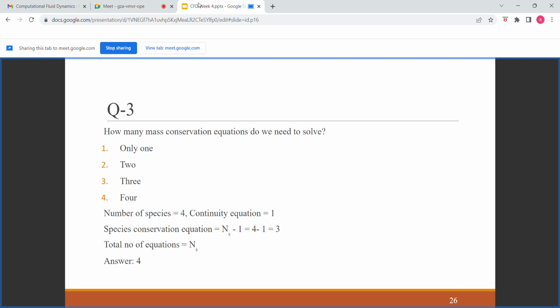But when everything is added together, we get one, so the number is one less than the number of species present. So basically 3 velocities u, v, and w, plus one pressure plus one temperature give 5, and mass fraction terms, where 4 species are present, give 3. So 5 plus 3 is 8. So with 8 equations and 8 unknowns, it can be solved.